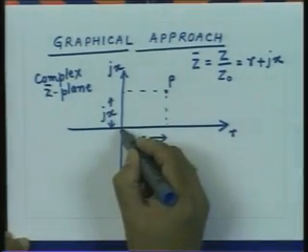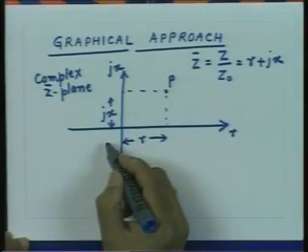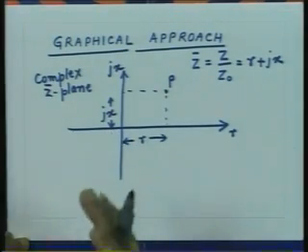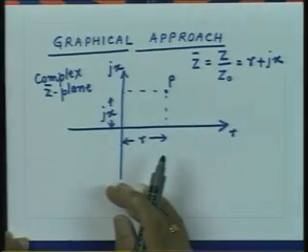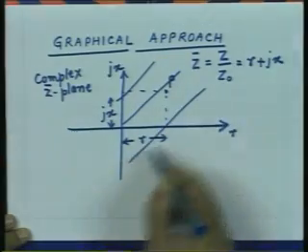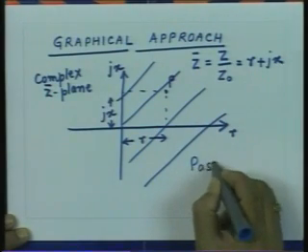Also, the points which lie on the imaginary axis, for which R is equal to 0, represent purely reactive loads. So, if I consider all points on the imaginary axis and the points lying on the right half of the imaginary axis, they cover all possible passive loads which one can realize on a transmission line. So, essentially the entire right half of the impedance plane represents the passive loads.